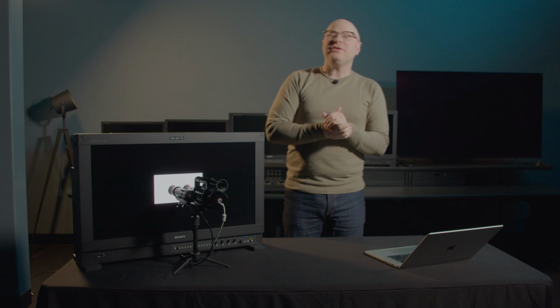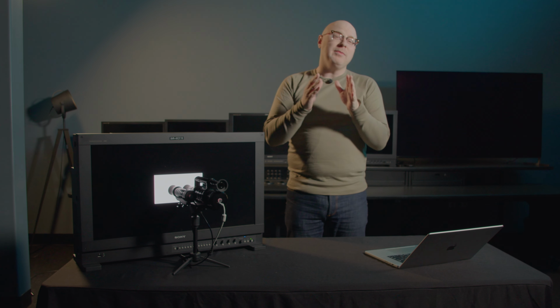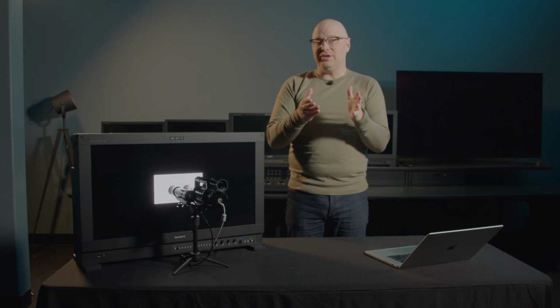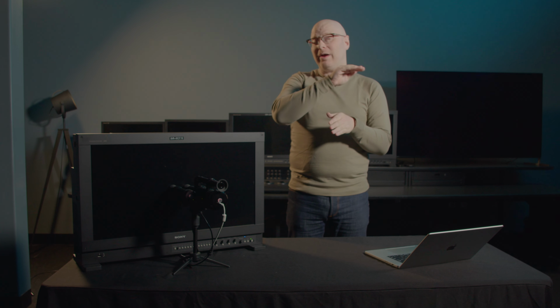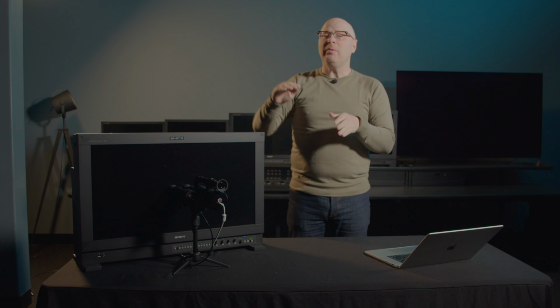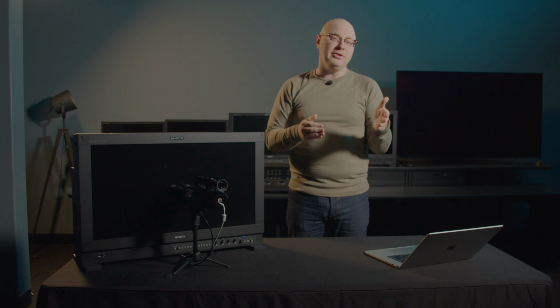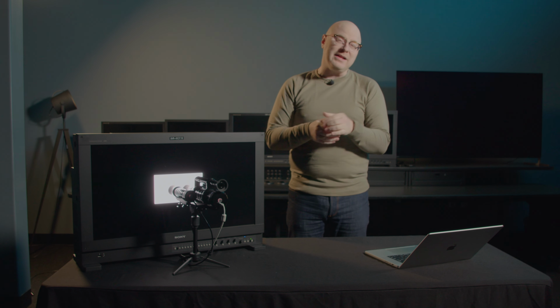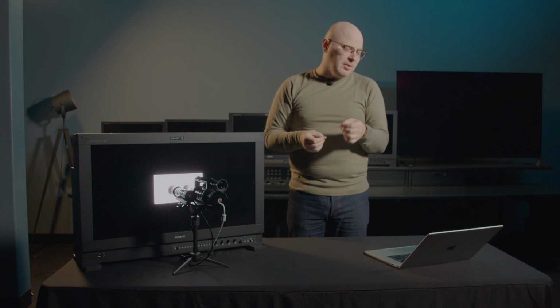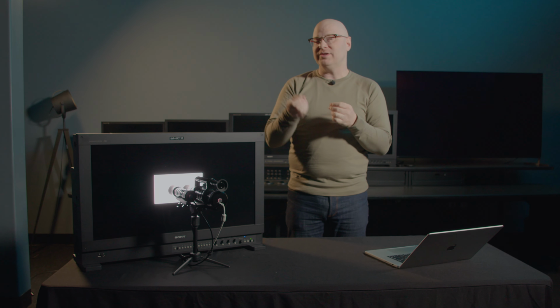Now it's important to measure the white balance in EOTF when we're measuring in SMPTE ST 2084 and PQ. Not only do we want to know how our white balance is performing throughout the range, but we also want to know how well we're tracking PQ. Remember, it's an absolute format, so it's really a bit for nit. We want to make sure that each level is hitting the luminance target level.